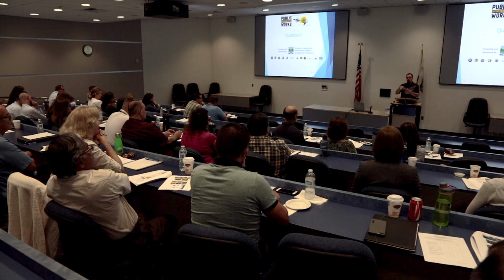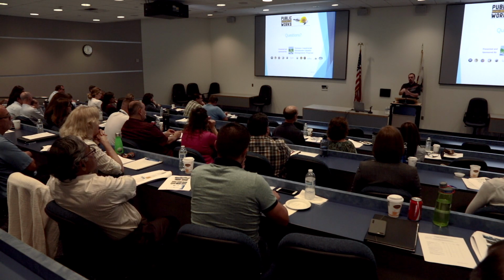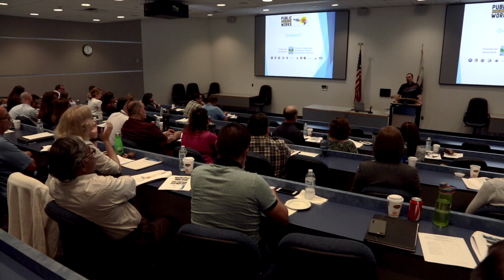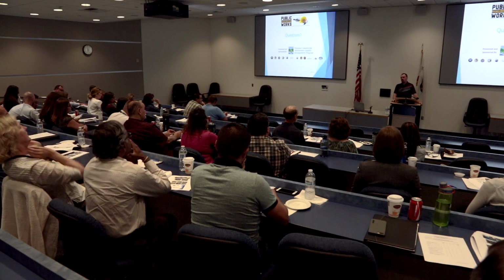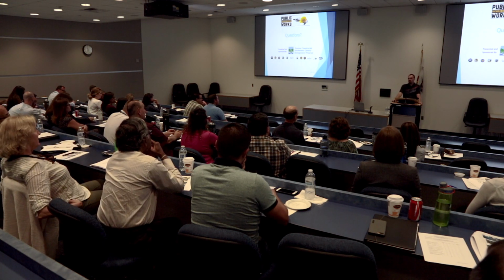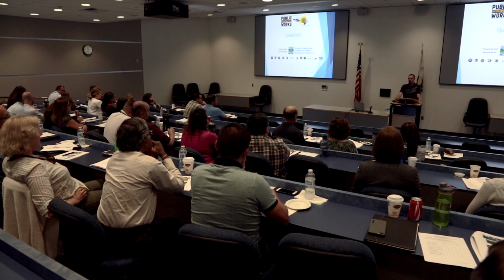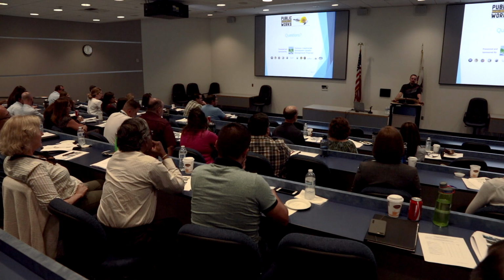They said, here's my project area, which is the parcel, 26 acres. My effective impervious area is 5% of that, which was more than the area they were disturbing. So they said, I don't have to do retention, I'm just going straight to swale. There's nothing in the TGM that says you can't do that, but I think that's a discretionary standpoint. From a common sense standpoint, that doesn't make a lot of sense to me to be able to allow that type of